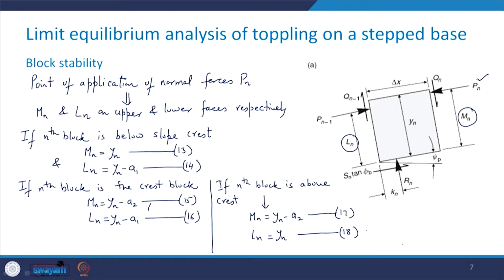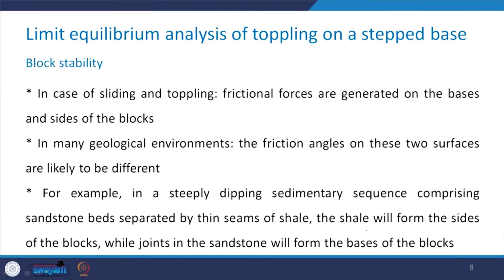Now, in case of sliding and toppling, frictional forces are generated on the bases as well as on the sides of the blocks. In many geological environments, the friction angles on these two surfaces are going to be different.